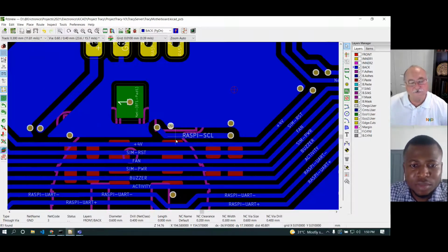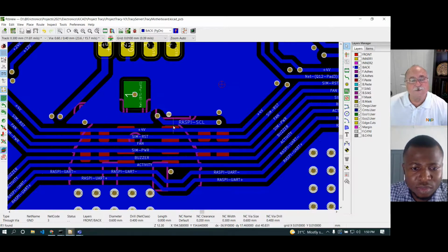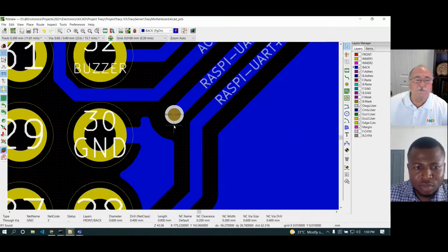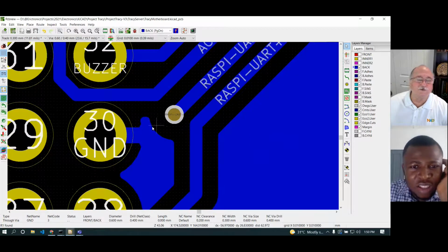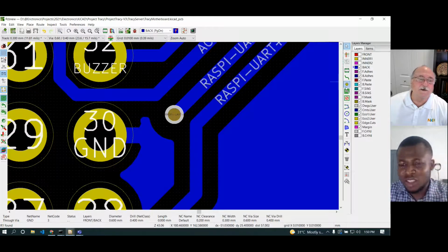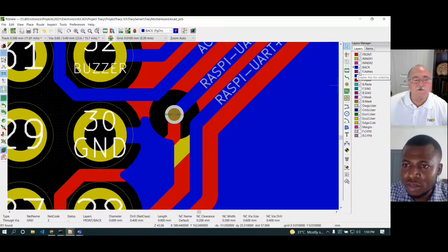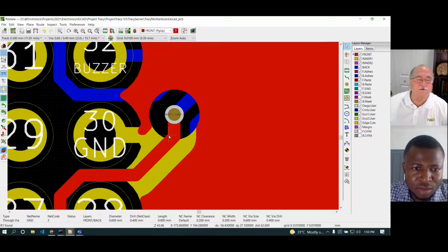Once we've established a good board stack up and placed ground flood wherever possible, the final step is to make sure that every place you see a via on a signal, there has to be a ground via very close to it. Now, in this case, you've got a ground pin, but I would still put a ground via here next to that. Because the next step is connecting all the pieces of ground flood that are isolated.